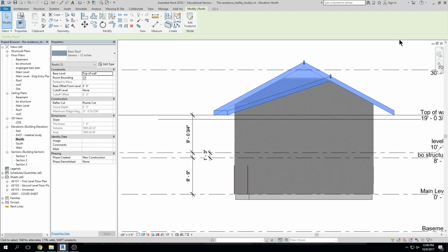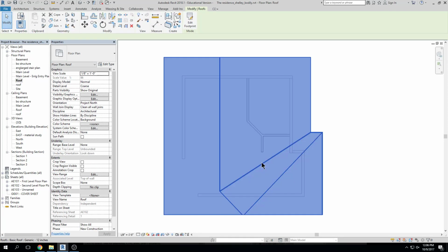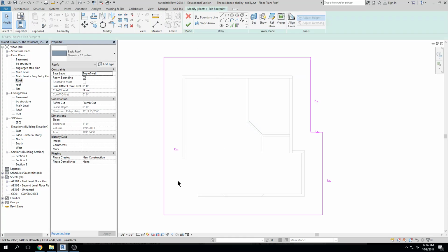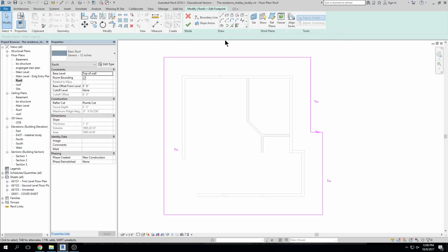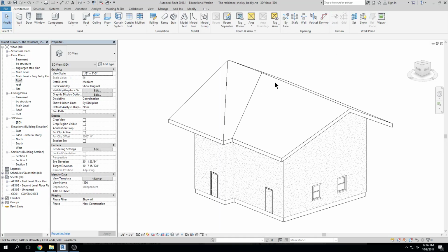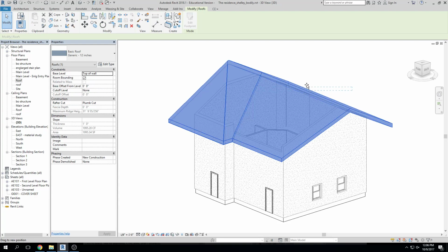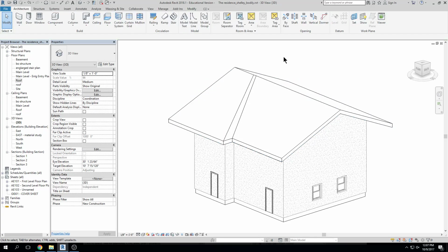So now when my roof is selected, let's see, my slope. Ooh, it's not giving me my slope. I'm going to go to my roof plan. Click. Ooh, that's really weird. Click, edit footprint. Let's see what some of these slopes are. That one's a 0. Like 129 over, right? So it's not calculating a definite kind of increment, right? It's just calculating whatever it ends up being when you pull on these roof lines, right? Okay. So I can go in and I can alter the roof line other than in a sketch, okay?